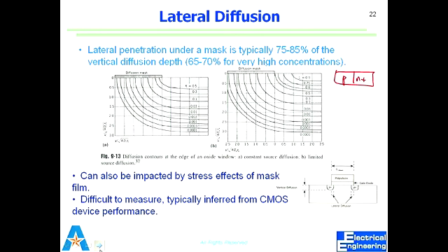So this silicon dioxide still has some structure, which has its own strain. So the strain of silicon and silicon dioxide would be different. That's a mismatch. Don't call it lattice mismatch, because of course one is a lattice and the other one is not. But there's a strain between the two, and the thermal coefficient is different. That's also a contributor to the lateral diffusion.